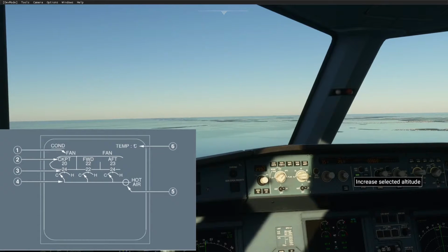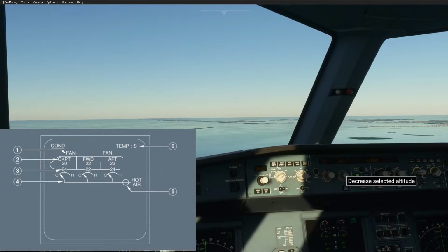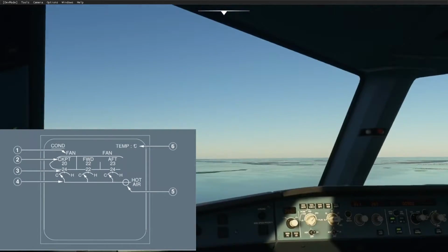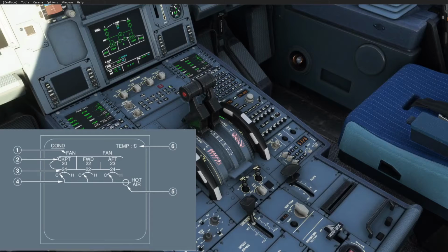Really, this doesn't have that big of an effect. I've been in a few aircraft where this has happened and this has failed, and honestly, it just makes the temperature go up and down a little bit more, but it's perfectly manageable. The trim air valves are what will supply this hot air, and each one of them is controlled by the relevant ACSC. The ACSC1 controls the cockpit and ACSC2 controls the ones in the cabin.